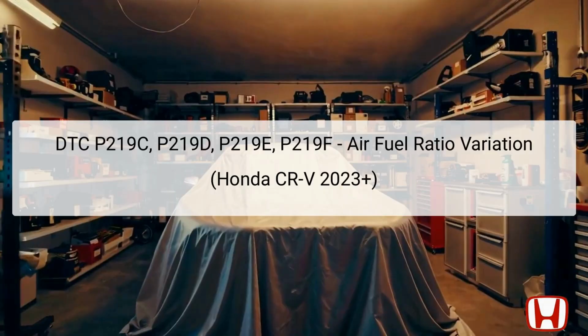The Diagnostic Trouble Codes (DTC) P219C, P219D, P219E, and P219F specifically refer to air-fuel ratio variations across the individual cylinders of the 2023 and later Honda CR-V models. Each code corresponds to a specific cylinder: P219C for cylinder 1, P219D for cylinder 2, P219E for cylinder 3, and